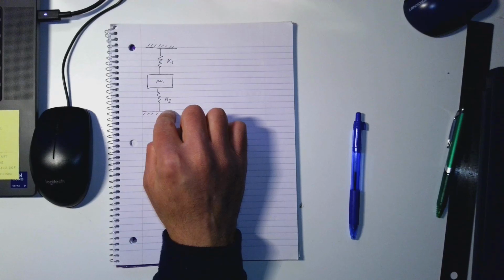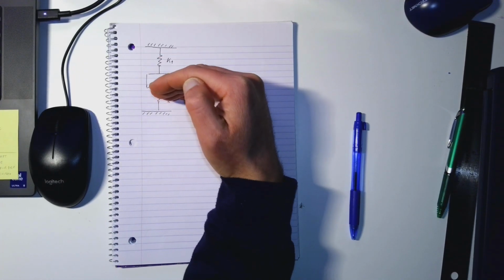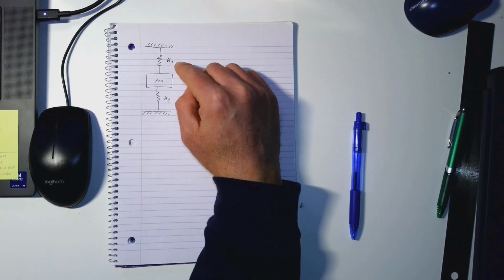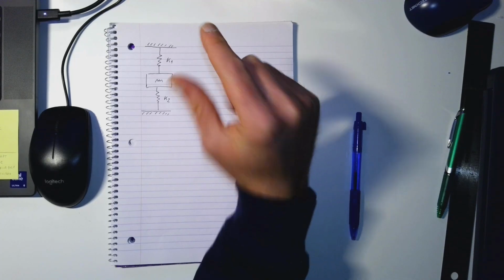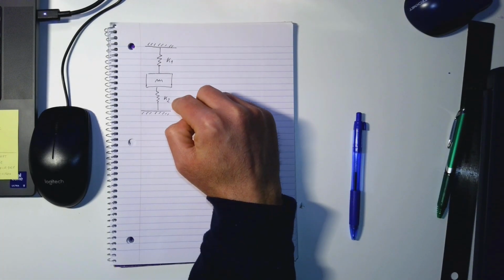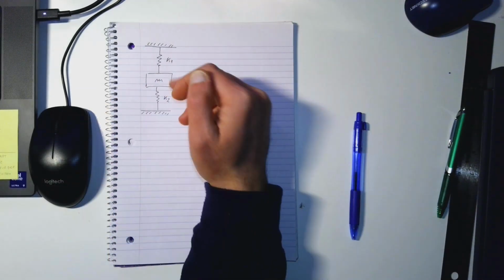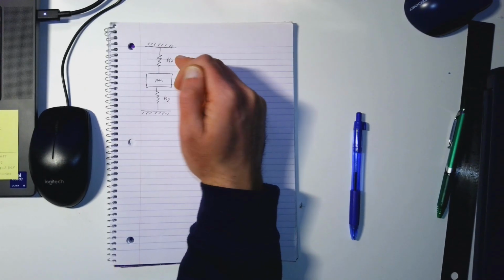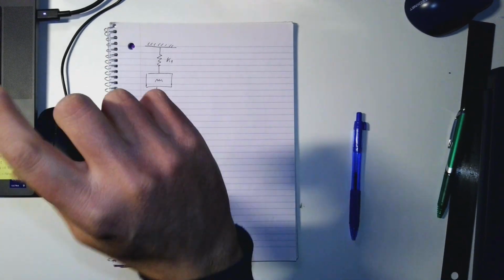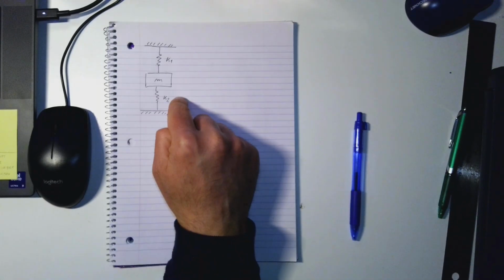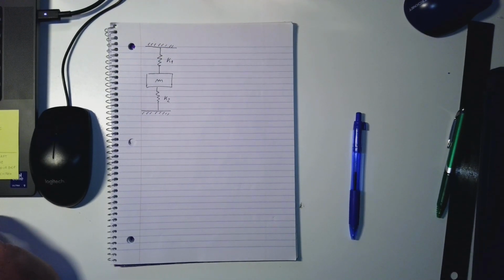In this case, we talk about springs in parallel because they are subjected to the same displacement. If the mass goes up by a certain quantity, the top spring is squeezed by a certain amount, and the bottom spring is extended by the exact same amount. Same thing if the mass goes down, it means the top spring is stretched by a certain amount, the bottom spring is compressed by the exact same amount. So in this case we are talking about springs that are in parallel.